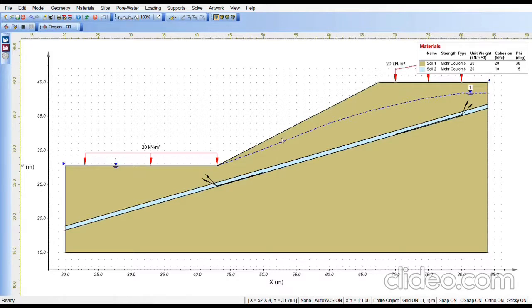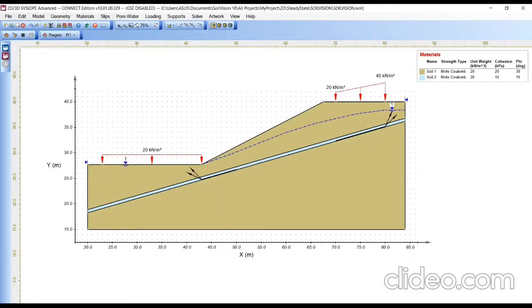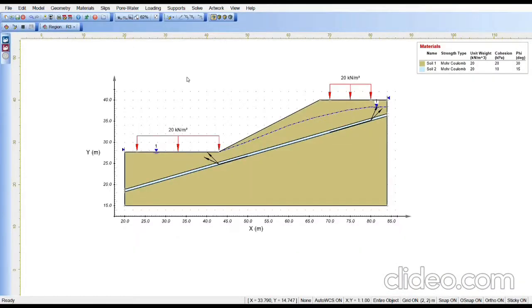To analyze the model, we have to choose the analyze bar. We have to click the solve tab, and then we have to analyze. This step is very simple: when the dialog box pops up and asks if we want to save and continue the model, just click OK.